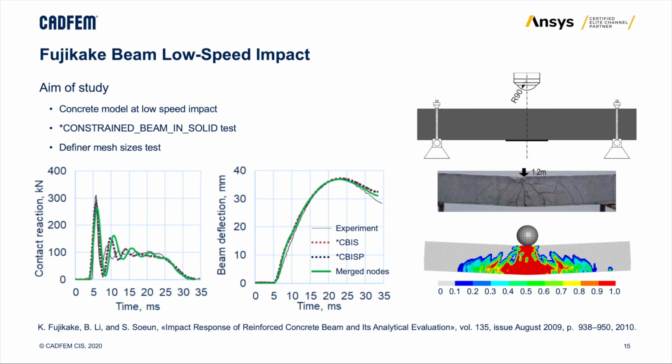We also studied the difference between the crack pattern in the real experiment and the damage pattern in the simulation. One of our main results is that constrained beam in solid works correctly and gives the same result as the merged node approach. So we can use this type of reinforcement coupling. We can also show that we correctly describe force reaction and beam deflection.